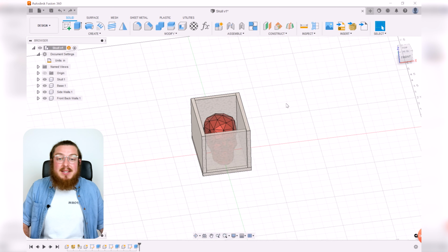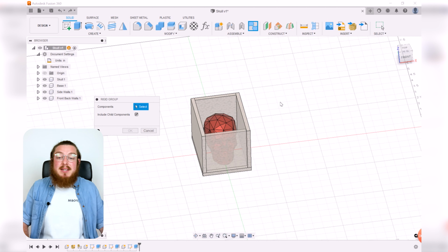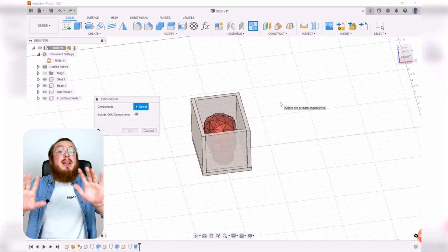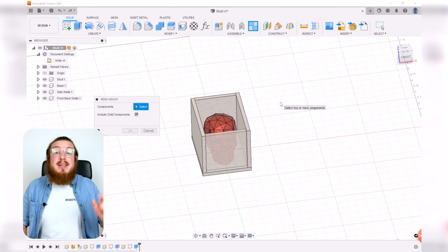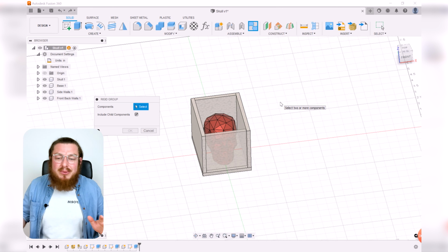But another really fast thing to do is add what's known as a rigid group. A rigid group basically says, hey, everything, stay in the right location. It's very similar to using the fix or unfix constraint tool in the sketch, where we don't really care about any dimensions. We're just saying, hey, stay in the same location.